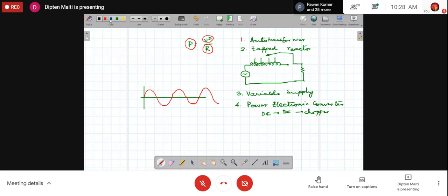Okay. So here, depending upon the requirement, we would use the first method. We can use this sort of structure where, by a known form of control, we can control the delay of the switching pulse, such that for the first positive half of the sine wave, we delay the switching and switch here on the blue line, and that means this much of the voltage would be applied across the load.